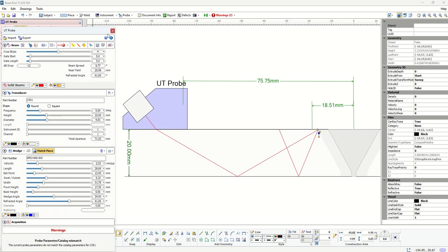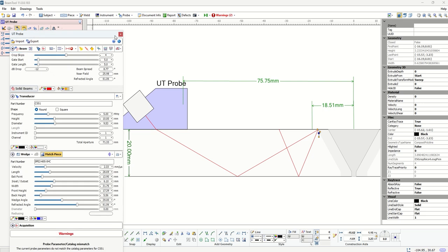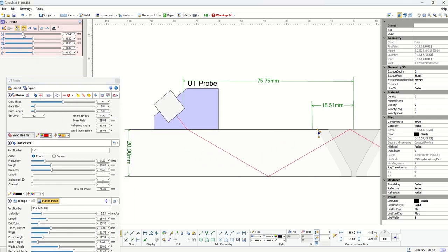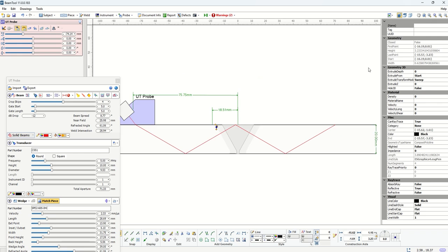But if we essentially move to locations where there is no interaction with a defect, we will see that we keep having this number of skips, and here I have 1, 2, 3, 4 skips. But other than skip, the other option we can use here would be distance from the element or time from the element.